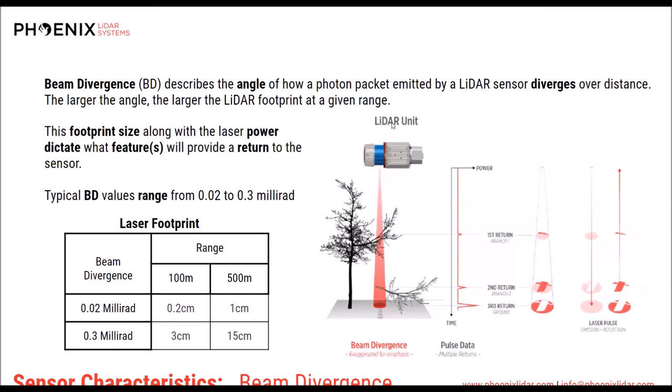But that additional range and pulse repetition rate creates, while they both have the same beam divergence, if you think of the VUX LR targeting the same feature from twice the distance, your beam divergence is twice that. So the effects of beam divergence in terms of power of returns, as we were just speaking of, is the main difference between those two systems.